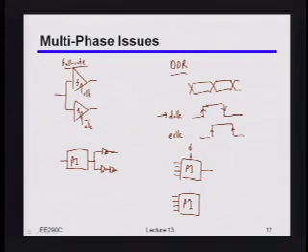So let's say this is some phi, I can make this phi plus 90, right? And then indeed, I'll get 2 output clocks, which at least nominally would be separated by 90 degrees. Okay, so this works. By the way, there's some people that do what's called QDR, which means the clock is 4 times slower than data. We could even do, and I don't even actually know how to call this, but I guess that would be ODR or octal data rate or something like that. So you can even do 8x interleaving, 10x interleaving. You can even go bonkers and do 100x interleaving if you really wanted to.